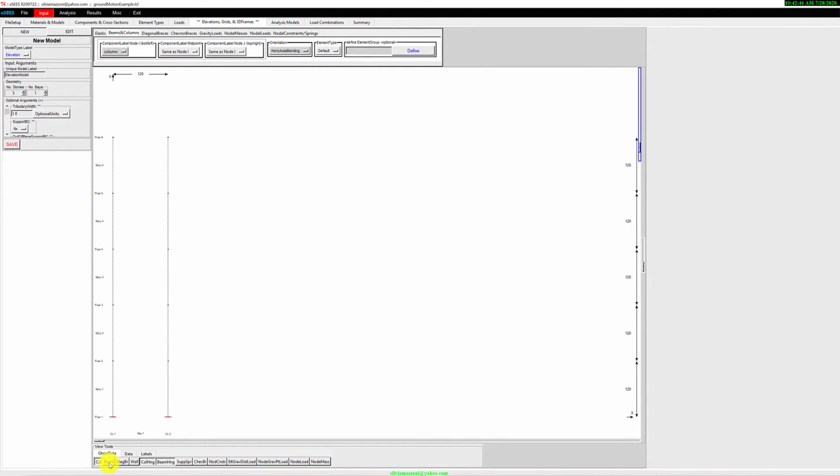You have to be really careful with that because they're going to get changed. Let's turn off the beams, so I'm only defining sections. With my shift key, I choose all the columns. Yes, I'm happy with those. And there they are. Now I want to define the beams, so I can turn off the columns, but I don't care. I'm done with that.